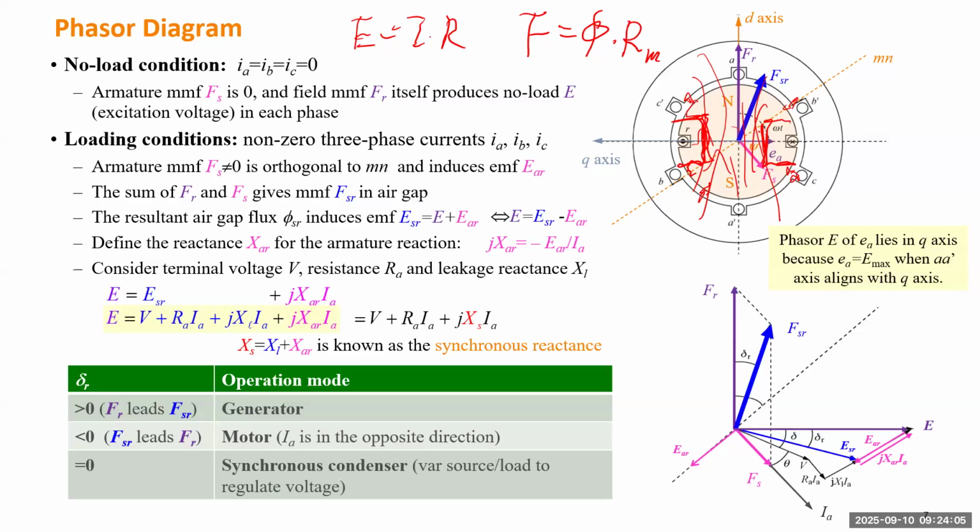So if the reluctance is bigger, phi will be smaller for the same magnetomotive force. If you have a fully magnetic material, Rm can be small and phi can be big. But for the air gap, Rm can be big and phi will be small.